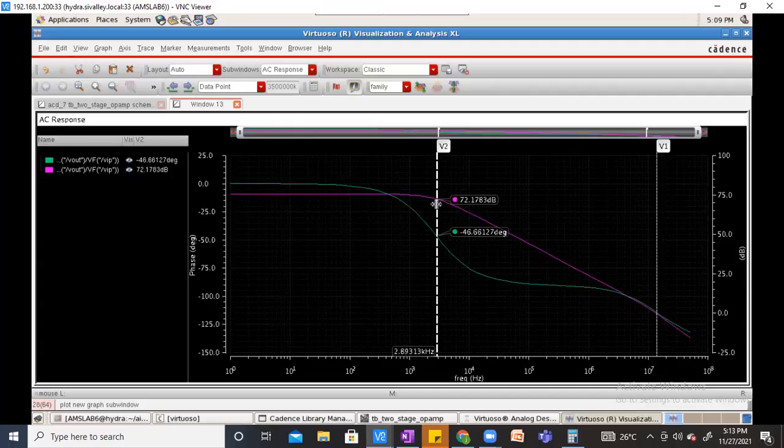The exact pole effect will be at the exact location, that is 1 kilohertz in this example, and the effect remains the same up to 10 times the frequency. So it is 1/10 or 10 times, that's the range. That's why we generally take a 5 to 10 range. The same holds good for zeros as well. Any questions?